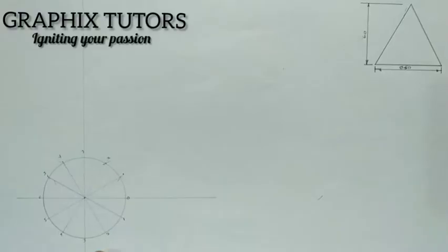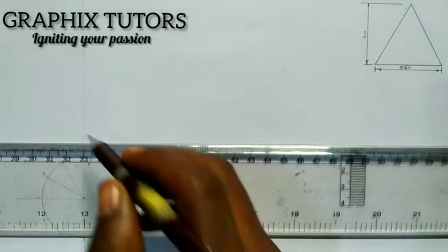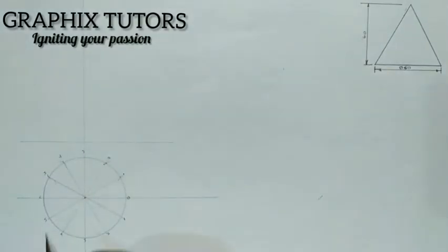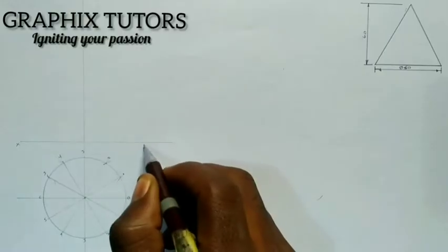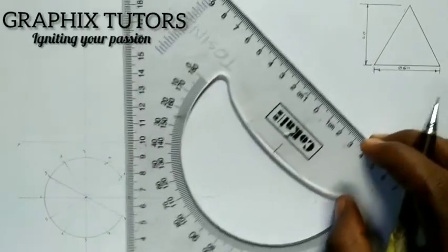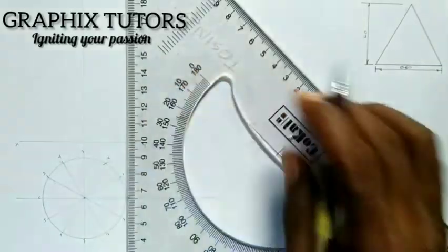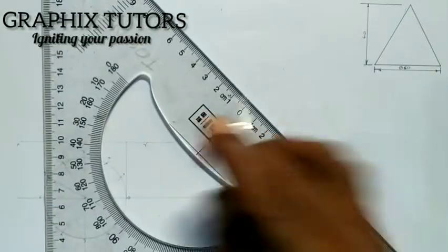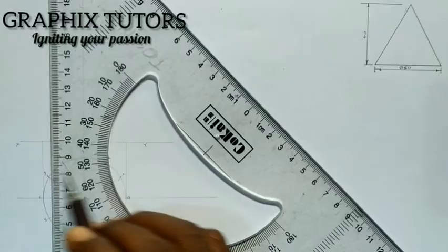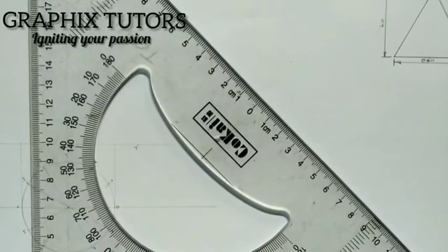Now the next thing I'm going to do is to project these lines upward. I'll just take an XY plane, probably very close to it. Let me call that my XY plane, right? So I'm going to project the edge of my circle to touch this plane. I'll project this also to touch this plane. So all those points, I'm going to be drawing them upward like this. So pick them up.